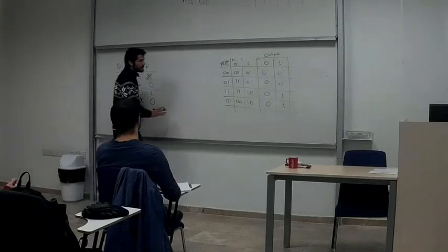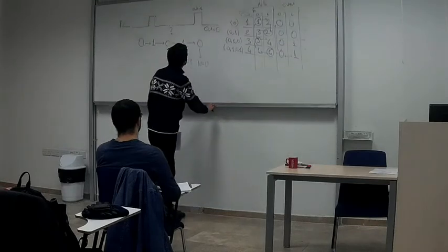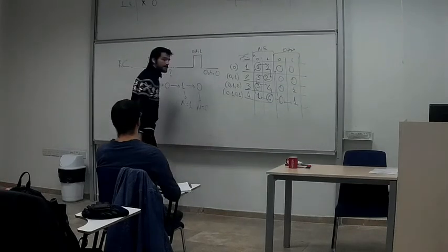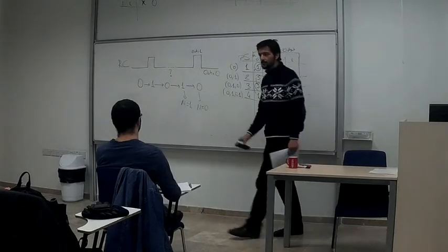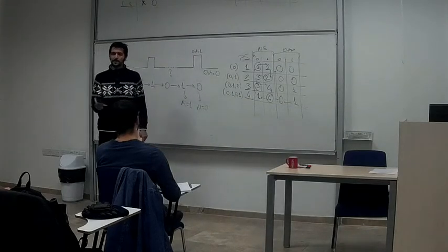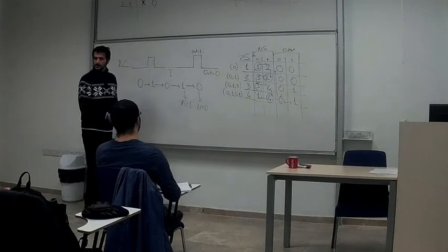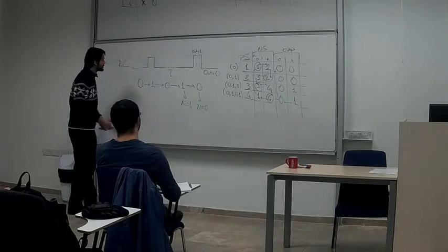Using this information and this table, I'm going to implement the SR-based K-map. So for each input, I'm going to have 2 K-maps, right? One for SA plus, RA plus, and then SB plus and RB plus, all of which have three variables, the RC and the present states.